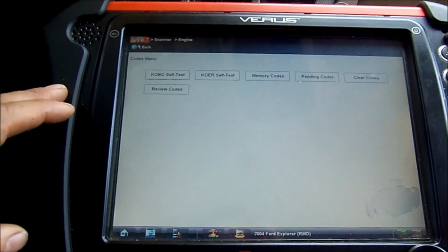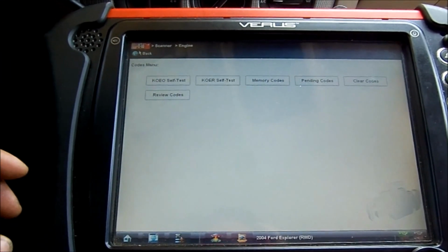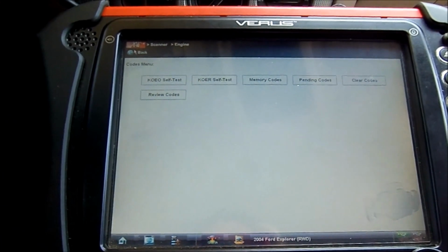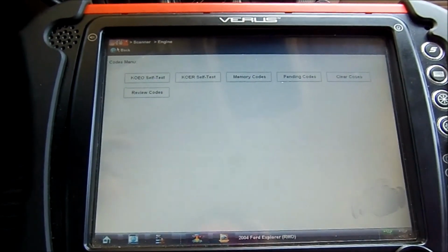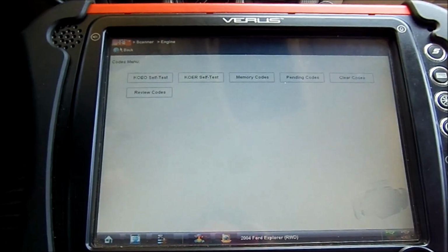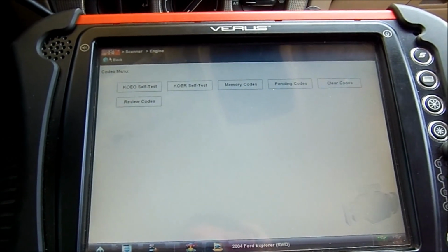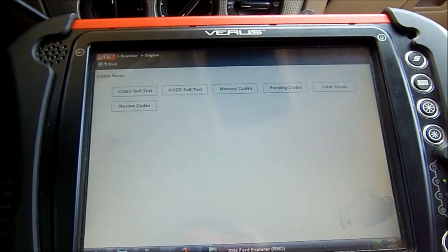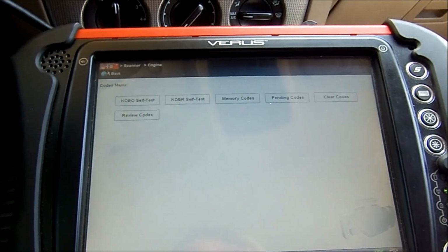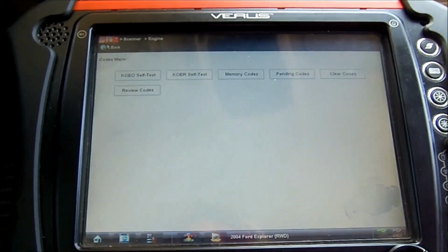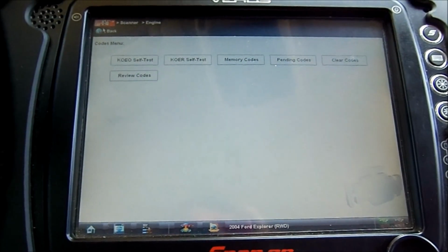So there are 3 things that can cause this. One is the EGR sensor module. It has the EGR valve, it has a DPFE sensor, and it has a MAP sensor, all built into one module. If that fails, it is going to give you this trouble code. The other causes are speed sensors: the speed sensors mounted on the transmission, and the speed sensors for the anti-lock braking system.